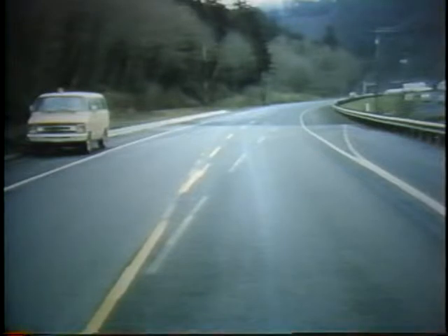Pavement markings that are no longer in use must be removed for safety. A change in roadway alignment or a change in line position requires that the old lines are removed. Now, here you see a situation where the double set of lines confuses drivers. Night is particularly dangerous because a driver could easily follow the old markings into the barrier.